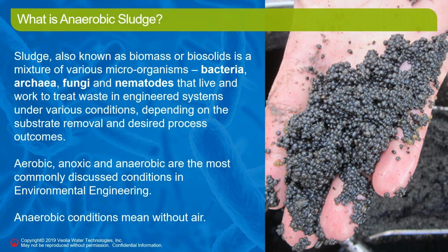It can also be called biomass. It can also be called biosolids. It can be called the guys, the stuff, whatever. And it's a mixture of various microorganisms, mostly bacteria, archaea, fungi, some nematodes. And what develops is a conglomerate of the above that's based on the conditions that it lives in and what it's trying to treat, because we're using these microorganisms to treat the waste in some way. That's either wastewater or waste solids.